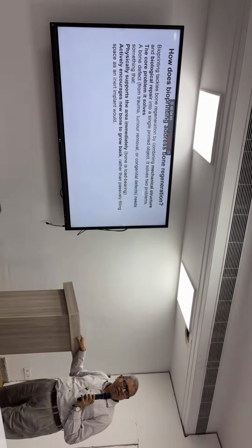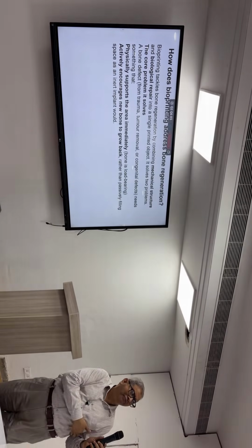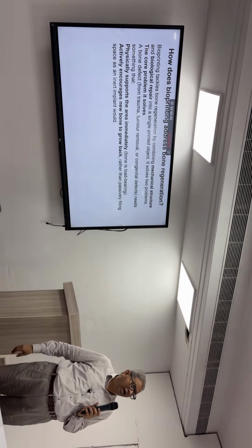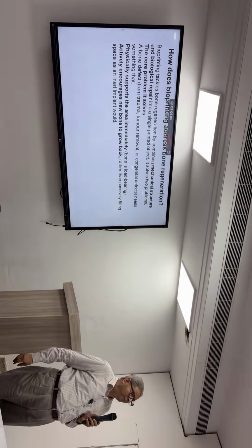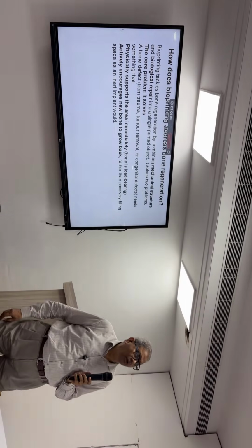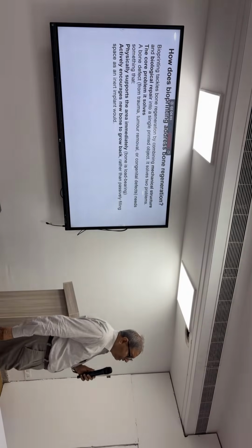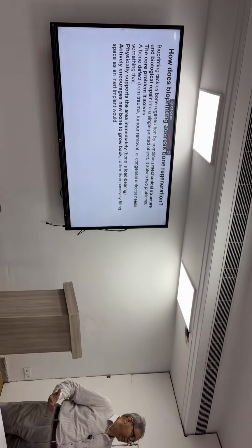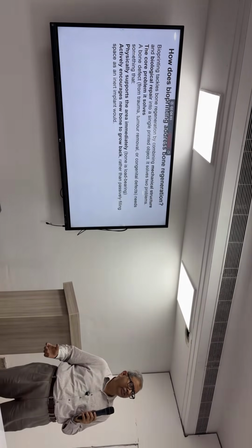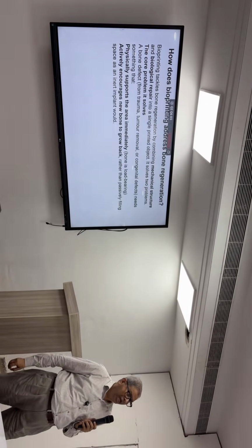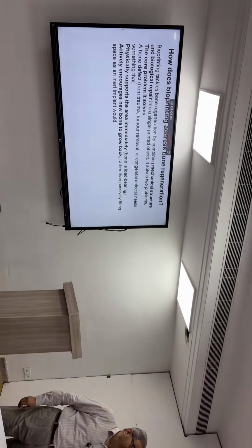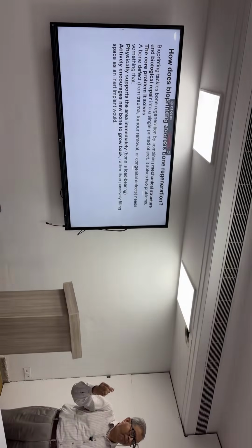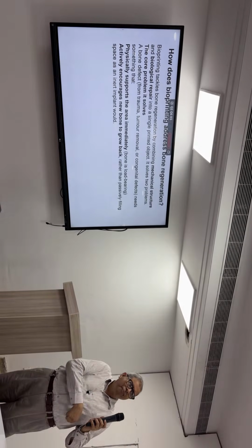I will tell you that some of the bones are being printed. Like your chest bones are being printed, but the problem is bone has a structure which has a lot of porosity, and everywhere it has a different strength. It is very difficult to have a material which has porosity and differential strength at different places. So generally it is done with PEEK, polyether ether ketone, and they print a bone-like structure which is implanted in the chest.